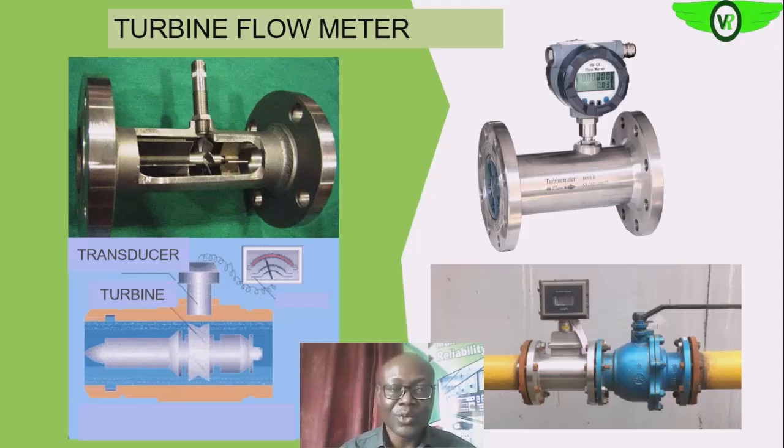So let's say between two pulses, 2 liters would have gone through the turbine meter. So if we have 10 pulses, it means that 20 liters of fluid have gone through that section of the turbine.